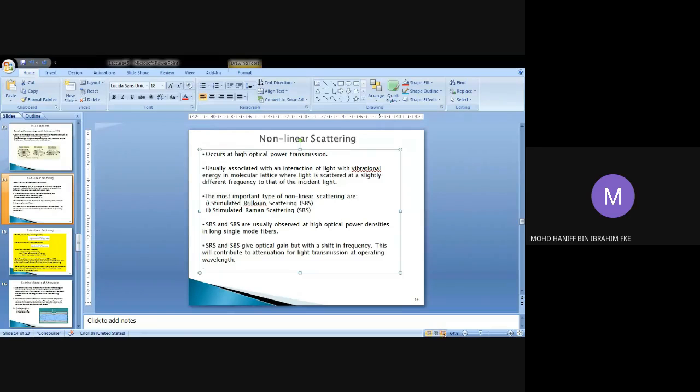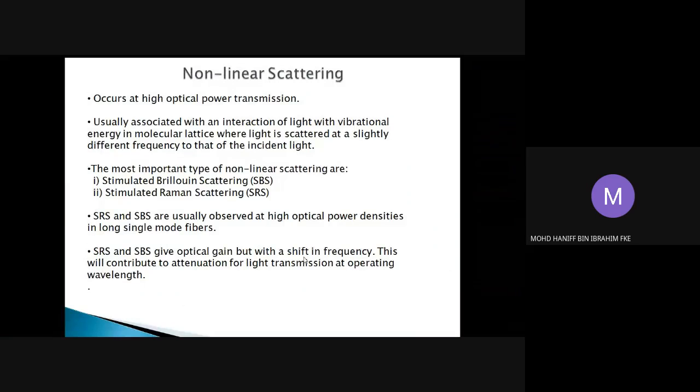Mie scattering is due to a larger size of impurities, right? And we have learned yesterday that, for example, in Mie scattering, some sort of roughness at the core and cladding interface should be one of the factors that contribute to the Mie scattering.